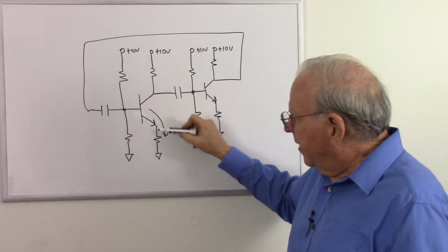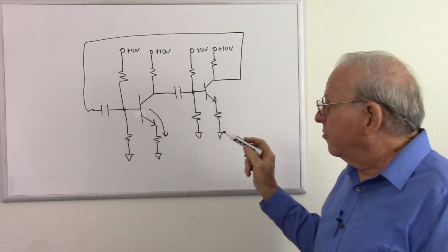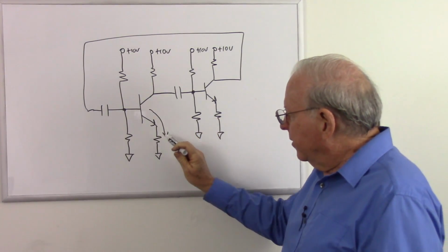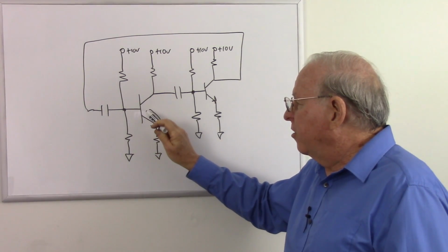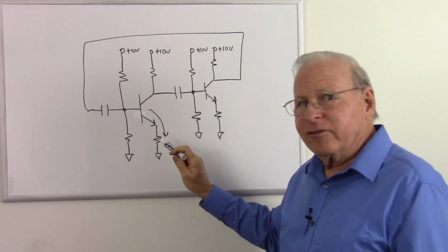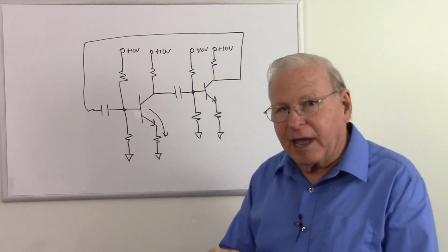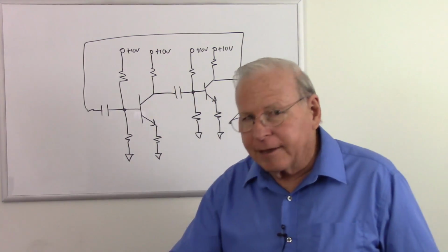And by the way, the size of that resistor is bigger than the resistor looks. When we talk about the small signal amplifier, remember that the value of this resistor, looking from here, is the HFE of the transistor times that resistance. And so it even looks bigger. So we get a lot of negative feedback just from having that resistor there. So that adds negative feedback.